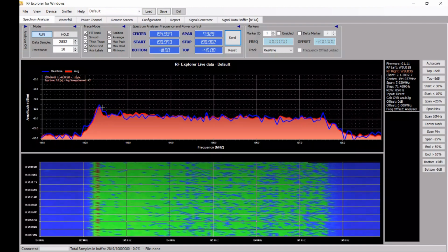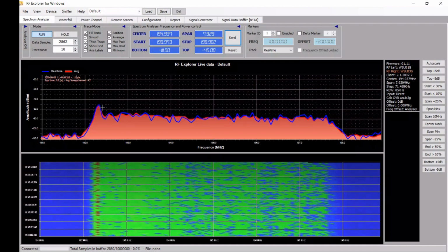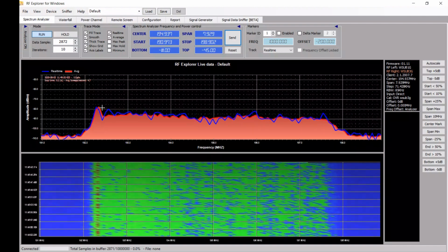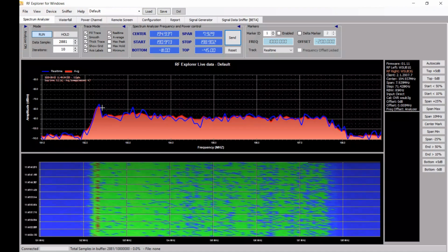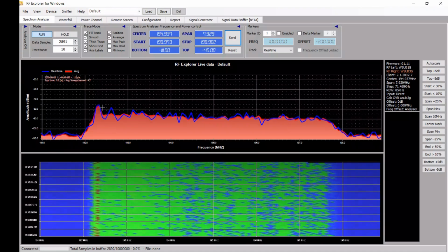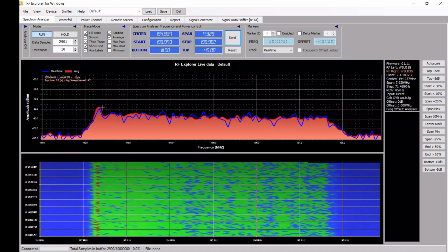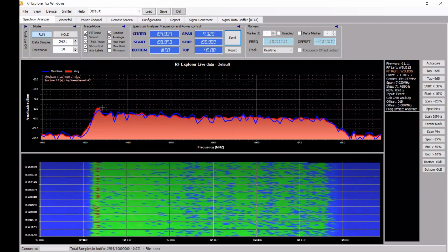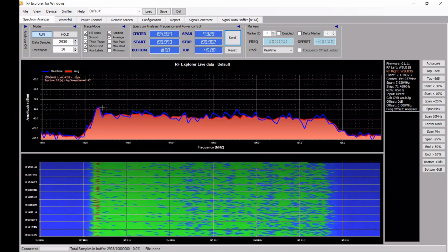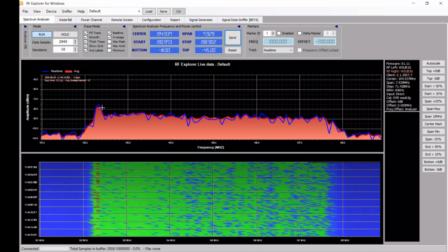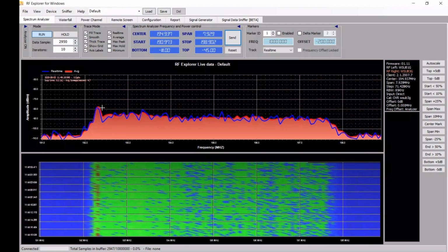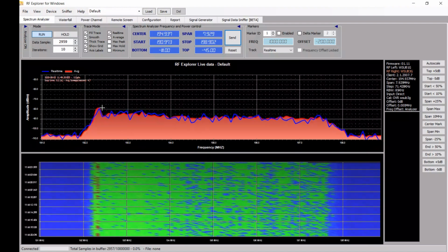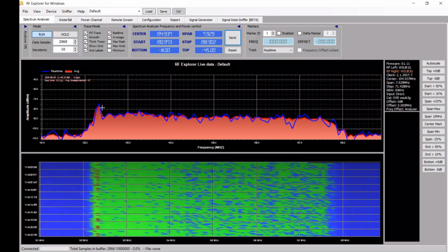So that's what you use amplifiers for. If you have some attenuation in your system, be it a long run of coaxial cable or, the more common reason, multiple receivers. For every receiver you add to your system, you drop signal strength for everybody by around 3 dB, depending on what splitters you're using. It could be even more, but anyways, that's where you would use an amplifier.